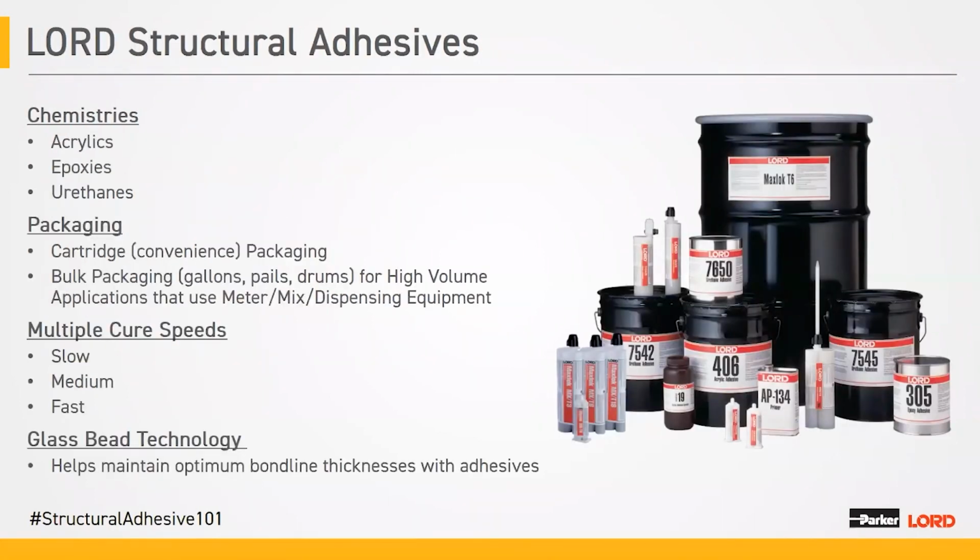Okay, now that we have a little bit of a background on some of the terms you might see on a technical data sheet to begin to understand how an adhesive works, I'd like to talk to you a little bit more now about Lord structural adhesives and some of the chemistries we offer: acrylics, urethanes, epoxies, as well as some of the packaging materials, cartridges or convenience packaging. You can see that in the picture here to the right. Bulk packaging being pails and drums and gallon kits, and then the convenience packaging being cartridges of material that can be readily dispensed on your application.